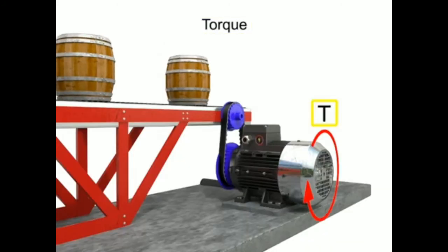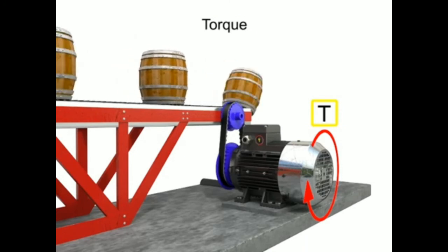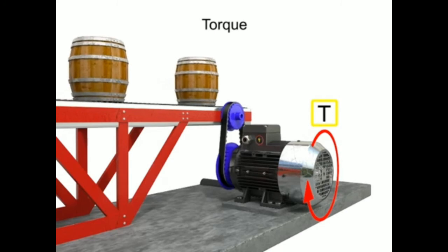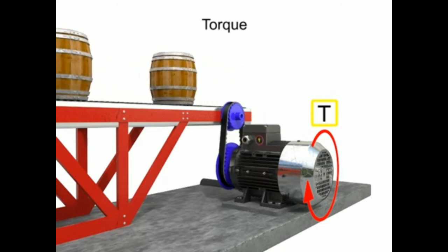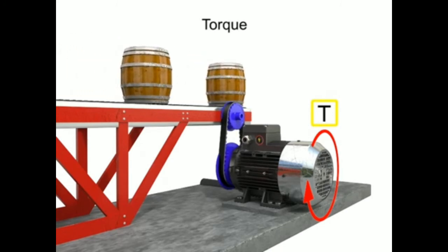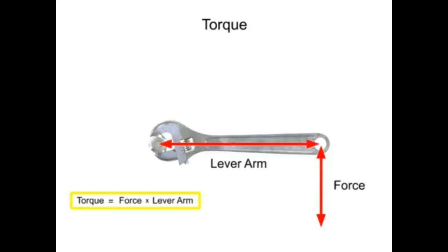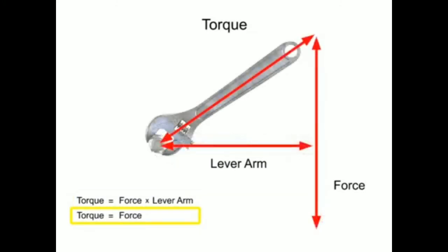A torque in a rotary device is the counterpart to force in a cylinder. Torque is defined as a strength which, if sufficient, will cause rotary motion in a rotatable body. Torque can be mathematically expressed as a force times a lever arm distance. When the force and lever arm are not perpendicular, the lever arm is calculated as r times the sine of angle theta.